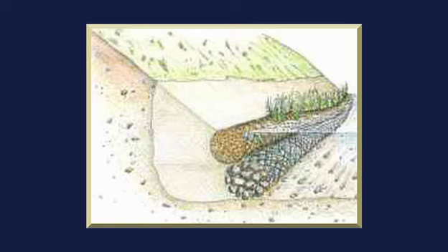Fascine rolls are similar to fascine sausages with a diameter of 25 to 40 centimeters. Weighted fascines are cylindrical bodies with a diameter of 0.8 to 1.2 meters. They consist of a 15 to 20 centimeter thick coat of brushwood and a core of rough gravel or crushed rock.